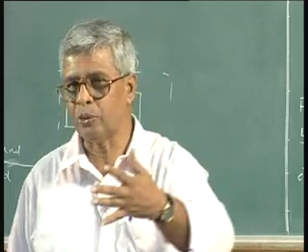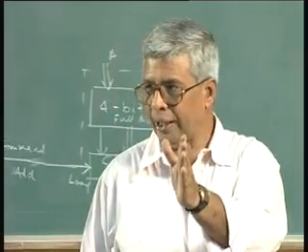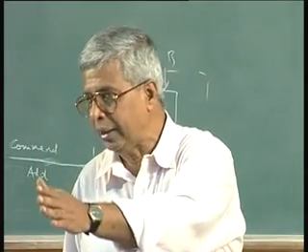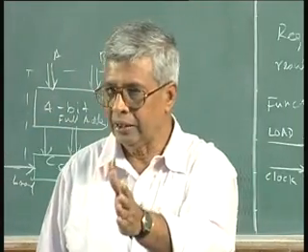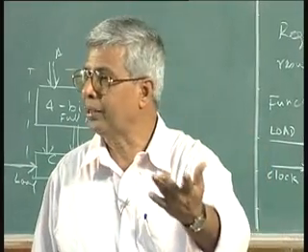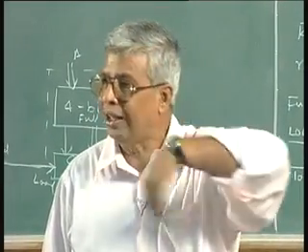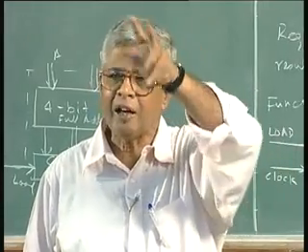or one of the simplest ways I can think of is, look at the last bit, the LSB. If it is a 1, add 1 to my B register, shift it by 1 bit, again look at it and then keep a count till n is over. When n is over, stop the process. That is going to be my control algorithm. The state graph will be decided by that. So I have a rough idea what I am going to do.